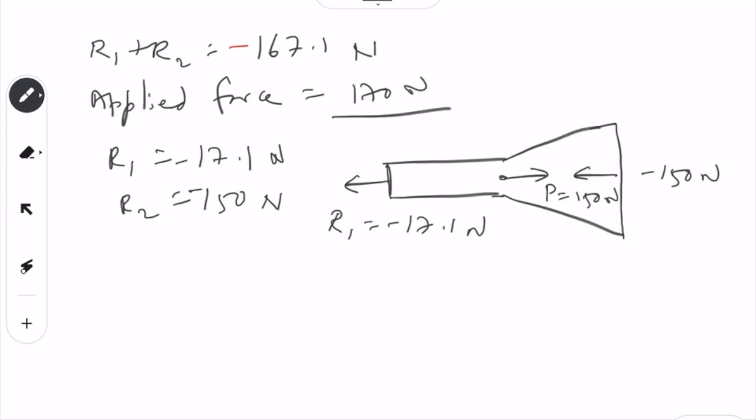Then you have this body force. So the body force is divided, basically. At 3 nodes we had 10 over 3 here, 40 over 3 here, and 10 over 3 here. So we had a total of 20 Newton divided at these points.